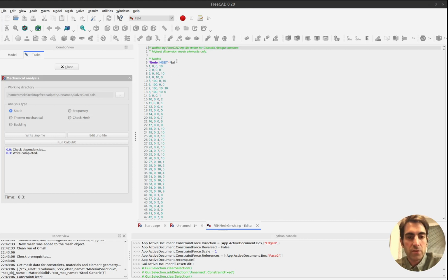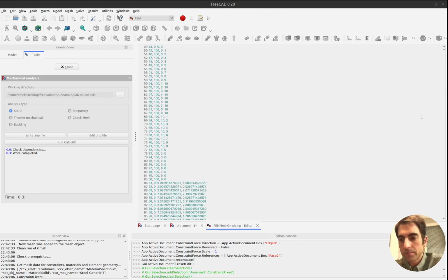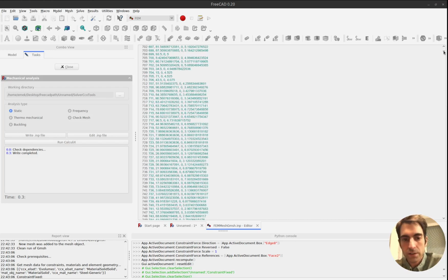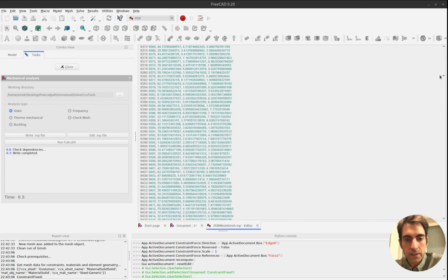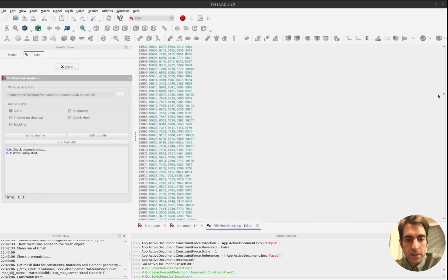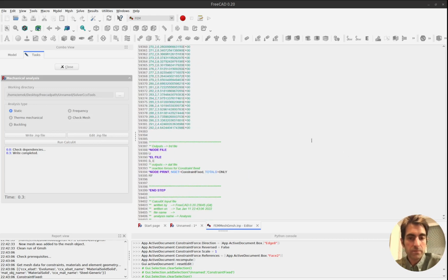So first you have the nodes, exactly as in Abaqus, a commercial FEM program, and it's a long list. Then you have the elements. Each element has 4 different nodes. So this is the element number 42,821, and it has these 4 nodes. Each node, for example 2,559, is on the list on top and has coordinates. Okay, so that's the whole topology with elements and nodes.